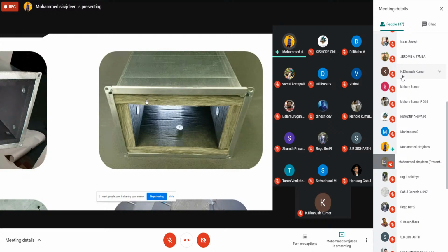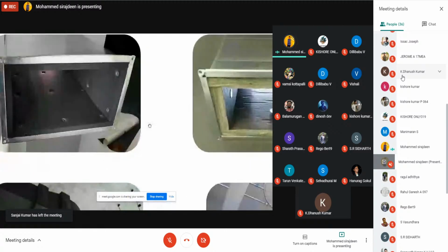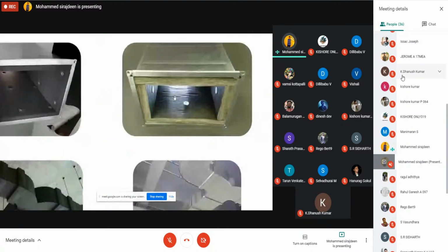The same is applicable for walls. For an equipment room, if the AC room is nearby the workstation or cabin, the noise will be more. So we observe the noise, and we have to provide acoustic insulation on the AC rooms. The acoustic insulation is recommended for a maximum of 3 meters from the AC outlet. More than that, the noise will not travel. The maximum noise travels till 3 meters, so generally it is recommended for 3 meters. Acoustic insulation only absorbs the noise.